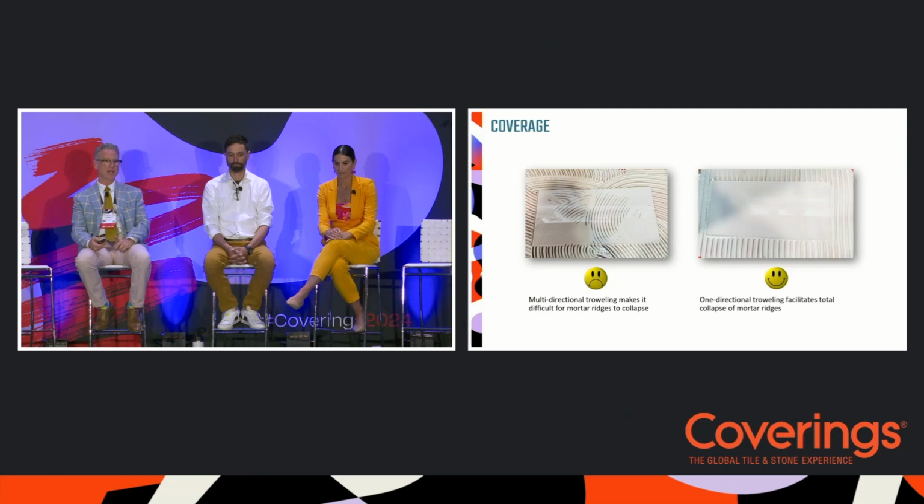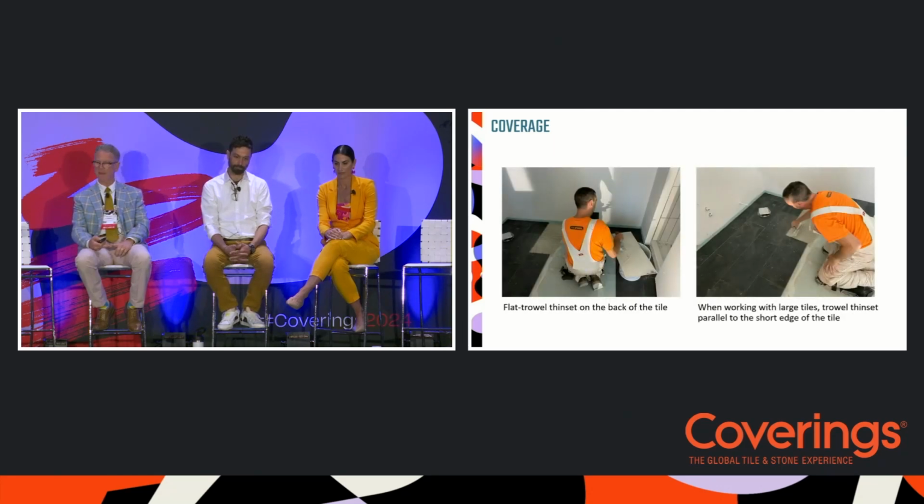And for large tiles, larger than 15 inches, it's best to trowel in the direction parallel to the short side of the tile, because those shorter mortar ridges are going to be easier to collapse than like a 4-foot long ridge. I'd rather collapse a 2-foot, or in this example, a 12-inch long ridge than a 24-inch long ridge. Okay.